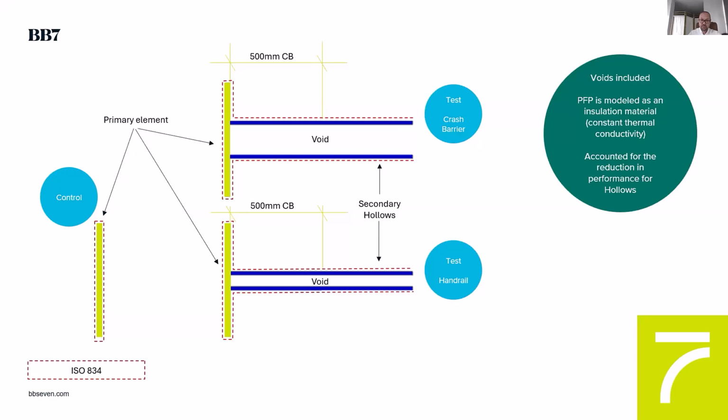Because it was an I section column and it was a hollow framing in, we also reduced the protection on the hollow, as intumescents typically, for the same DFT, do not behave as well for a hollow as they would for an I section. Basically the same DFT would not provide the same insulation for nearly all intumescents on the market. So we accounted for that in the model.